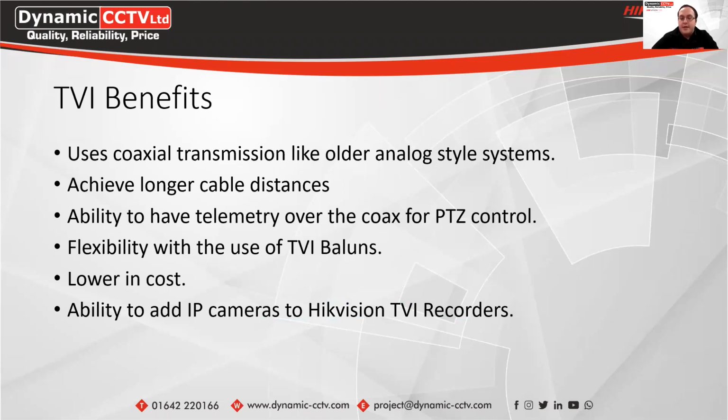So the benefits of the TVI range is you don't need to replace the cabling from legacy systems. They're based on the analog technology using either coaxial cable or Cat5 with balun. If you're using balun, you would need to replace them for TVI balun or POC friendly and AOC friendly, depending on the system that you are using. But a lot of the times you can use the existing cable on site as long as it's high enough quality to actually handle the TVI transmission.